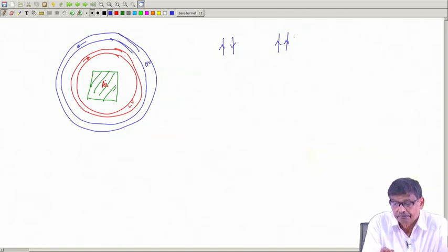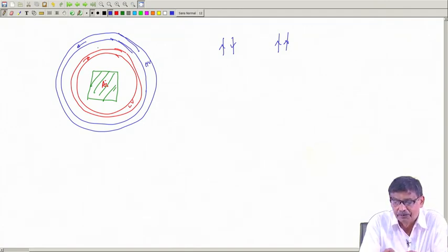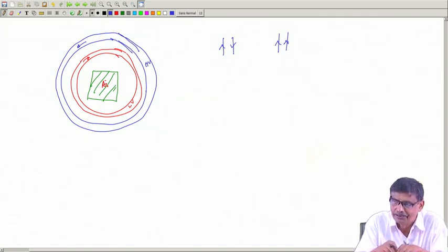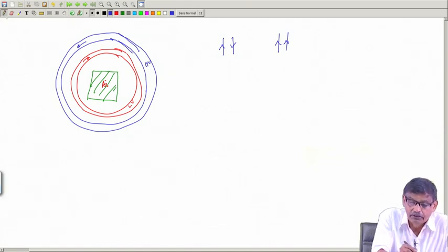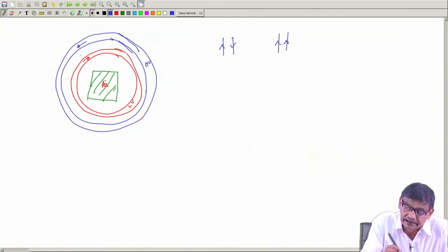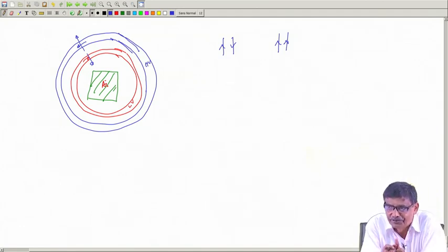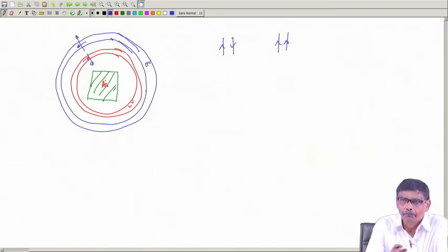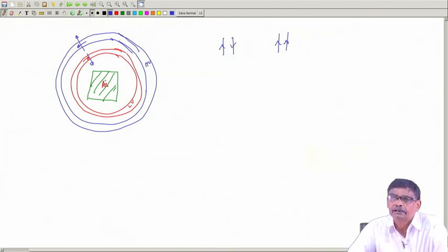That means this LV coil just cannot stay alone. There will be some bobbin sort of thing over which this LV winding is put. So, when normal load current flows, nonetheless there will be a force of repulsion acting. What will be the direction of the force? This way. That is, the LV winding will be squeezed towards the core and this will try to go away. So, you have to take proper fixing up of the coil, so that they can withstand those mechanical forces at